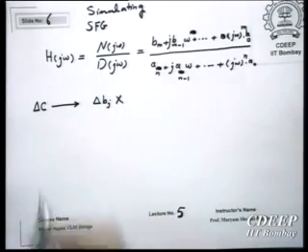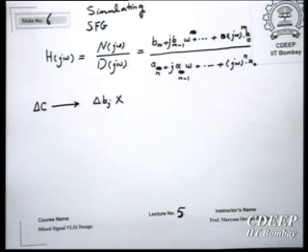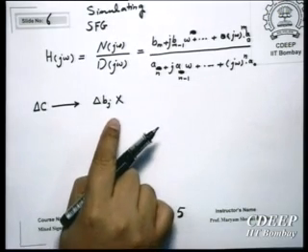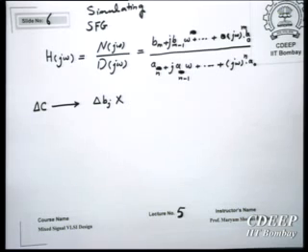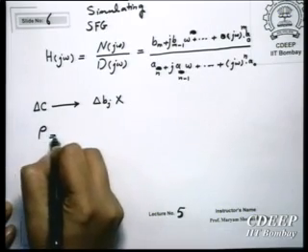What happens is, if you have a delta C, that effect will be translated everywhere. Therefore, all coefficients will change. This is one of the problems with these filters. However, in Schaumann's book, there is a theory. It has explained exactly the theory, and it has proved that if we have variations, if we design the filter in such a way that rho is equal to 0.